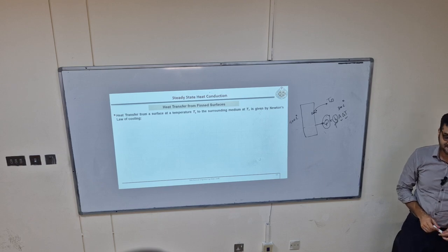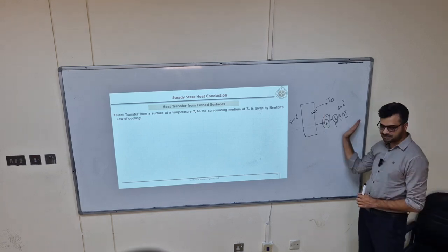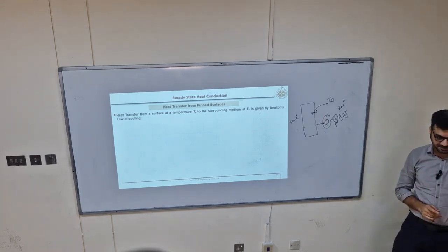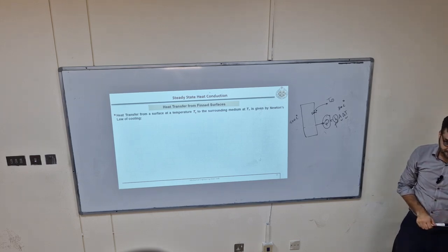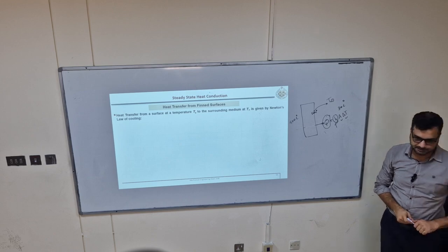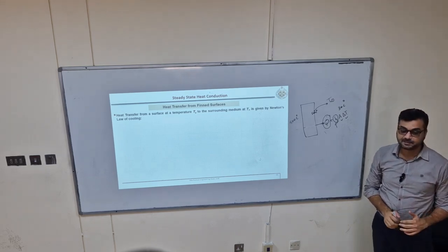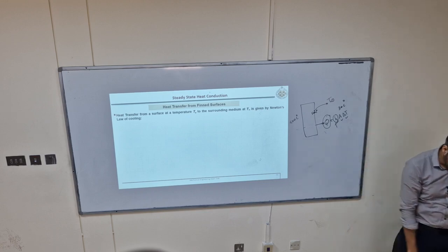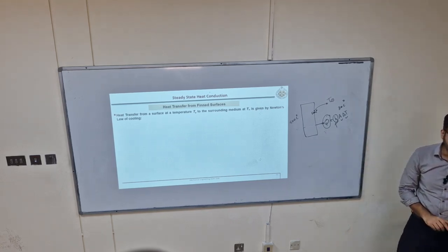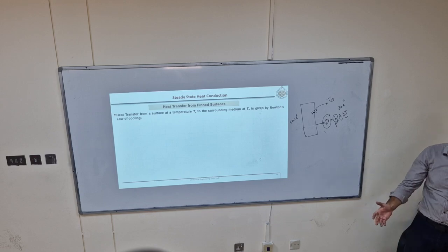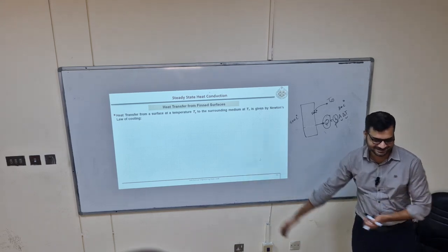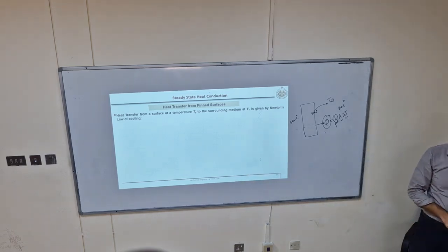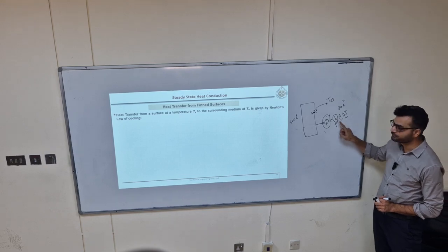Okay. What about this one? No, we are talking about the air side, the ambient side. In this air conditioner, what is the ambient? Air on the inner unit and also in the outer unit. In a car radiator, what is the cooling fluid? Water is losing heat where? In the radiator. Air. Again, air. Can we replace air with something else? Yes, we can, but it will be very expensive. You will be using another water stream, and then you have to cool that water. Okay. So it means air you must use, but with air you have certain restrictions. You cannot get very high H.